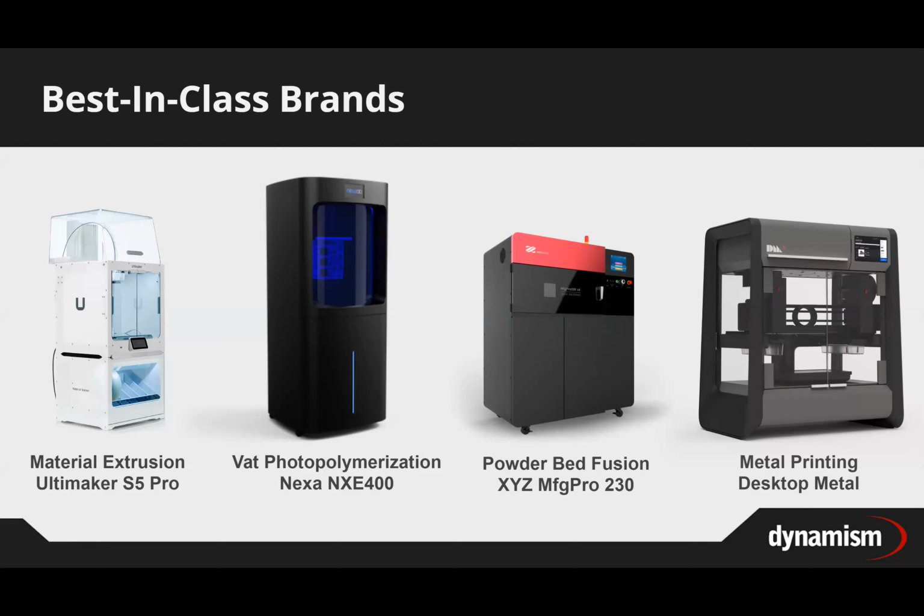Ultimaker is a great prosumer desktop option for material extrusion. Next I have Nexa for vat photopolymerization, which is a really interesting option. It's one of the world's fastest 3D printers at 1 layer per second, and it also has an extremely large build volume compared to a lot of the other SLA and DLP brands. Also on vat photopolymerization, if you're looking for more of a desktop option, Formlabs is a great option as well. Powder bed fusion, that's the SLS, and then Desktop Metal.